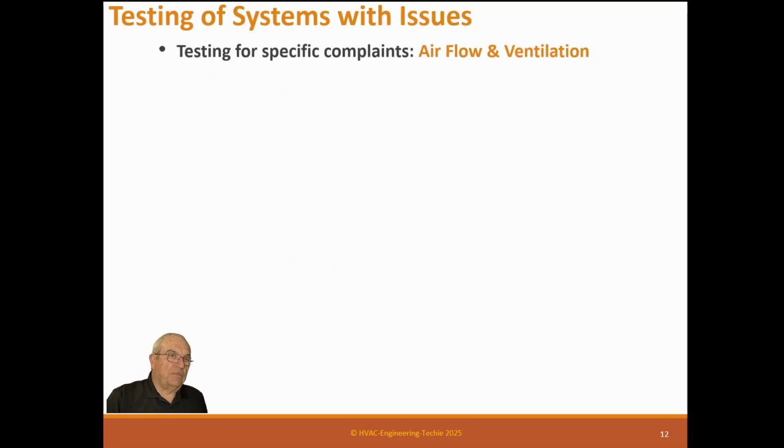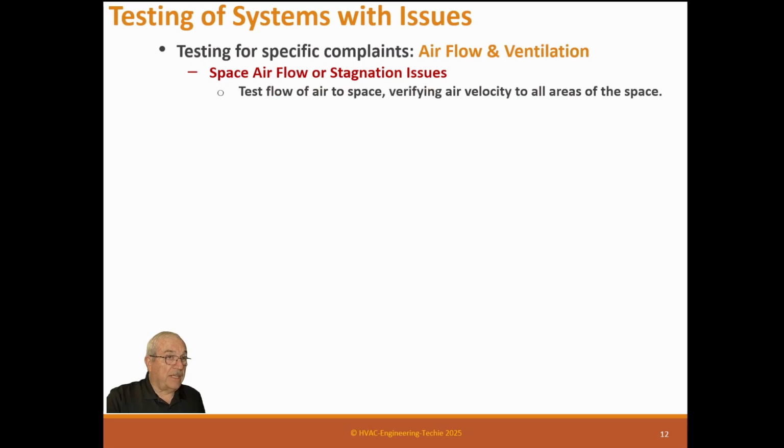Testing for specific complaints, airflow and ventilation. One of the complaints is, man, it's stuffy in here. Well, stuffy can mean we don't have enough fresh air, or it can mean we don't have enough ventilation air, because people are more comfortable if they have air velocity across them. If there's no air velocity, then it will seem stuffy. So that's what we're looking at for airflow or stagnation.